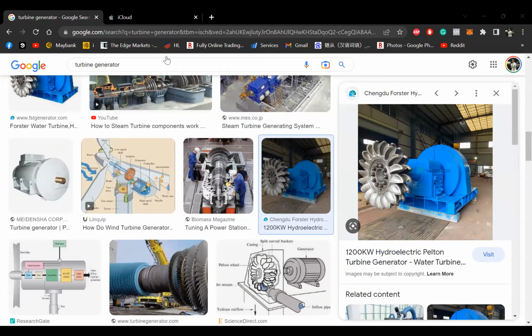So in reality, it will not only have one magnet inside. Even if you want the coil outside, can, because it doesn't matter if it's the magnet cutting through the coil or the coil cutting through the magnet. Now, ultimately, the idea is you need the magnetic field to cut through only, right? So in reality, even if you put a magnet inside, usually they'll have like maybe 6 or 8 magnets inside, so that every time the coil spins, it will cut through more magnetic field lines also. You get what I mean? Yes, it is possible.